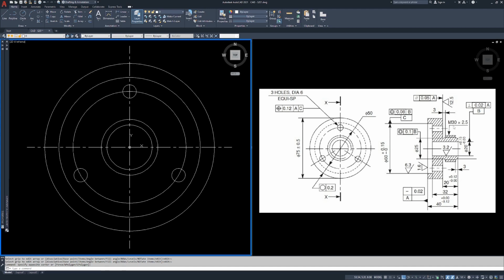So this drawing over here does not exactly look like it was drawn to scale. It might have been squished. For argument's sake, we're going to say this inside hole, this small circle here, diameter of 20. This larger circle is our diameter of 25. We're actually just going to use this M30 and make that a 30 unit diameter circle. So we're going to offset again, 2.5 again. We're going to offset it out.